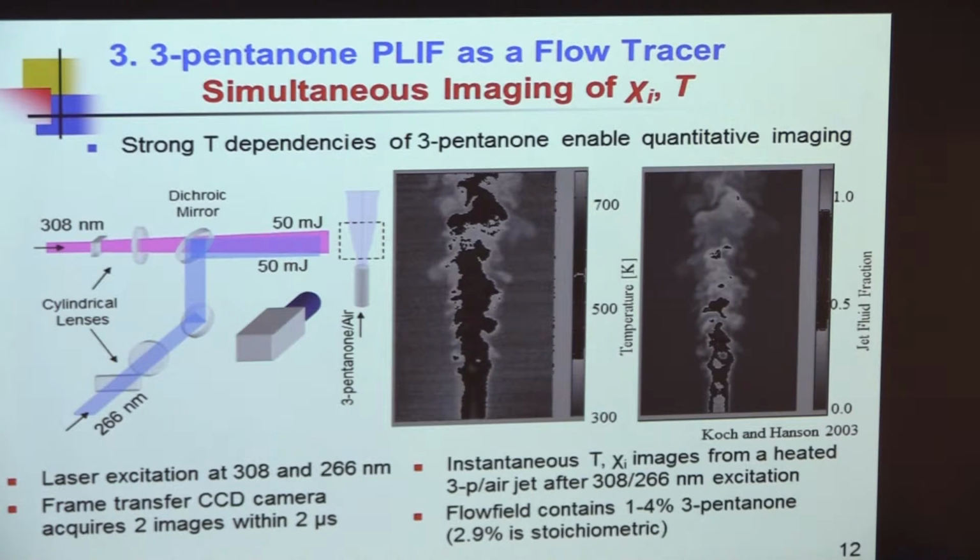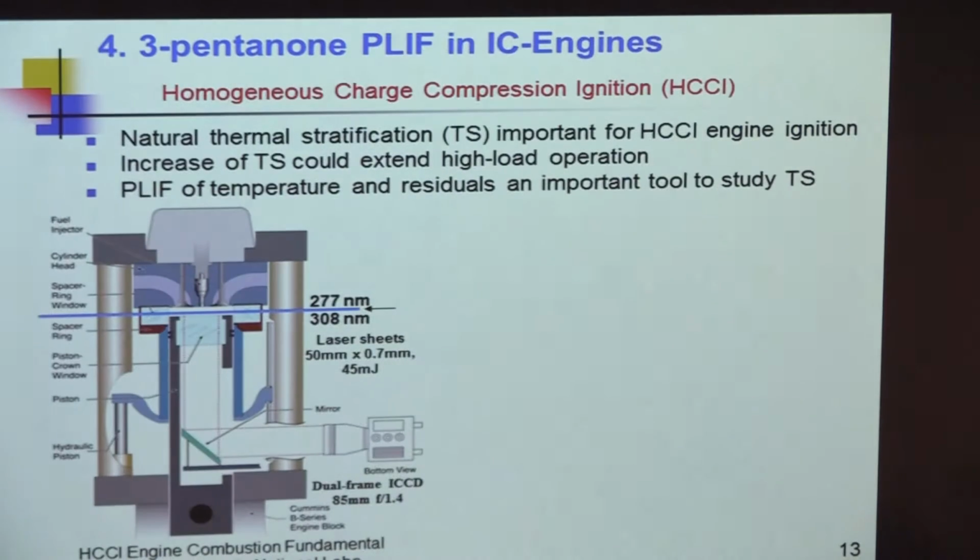That's a good scheme. You could just use the same scheme in a compressible flow field also, because the temperature would be independent of the pressure. And from this you would get the partial pressure of the species rather than the mole fraction. But if you knew the pressure locally, you could convert that to a mole fraction. So that's a pretty good idea.